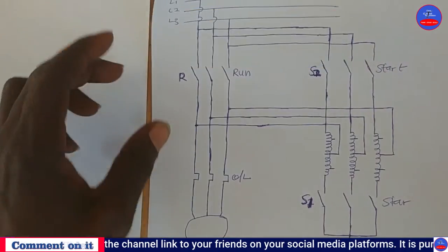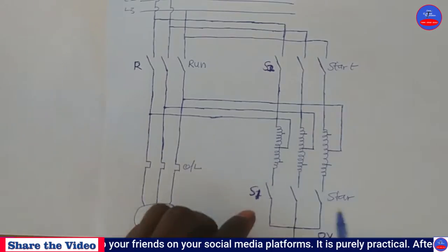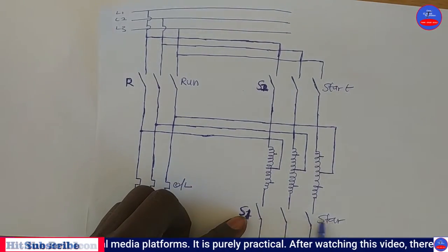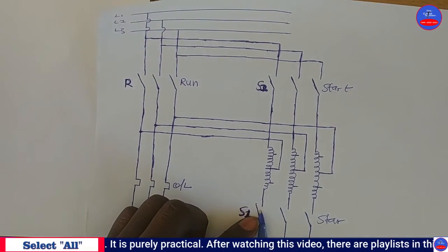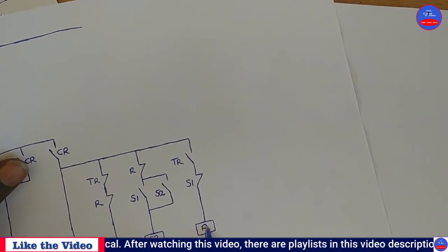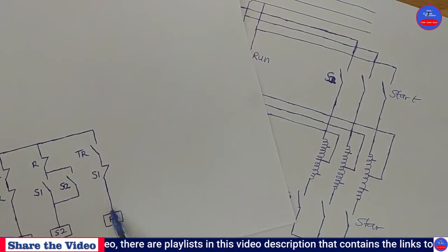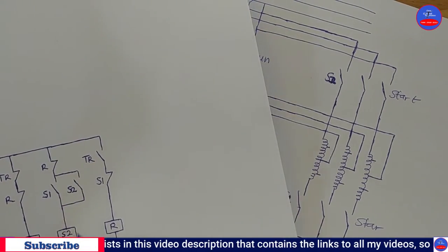So it means that always when the timer preset time reaches, the start contactor will go off, but it shouldn't go off with this one. The two of them shouldn't go off at the same time. This one will go off first. We call it closed transition. So when this one goes off first, the timer contact will energize the run contactor, so this side will also close. So we have a close here. When this one energizes, its contact here is going to open to de-energize the S2.